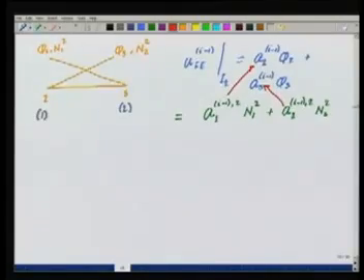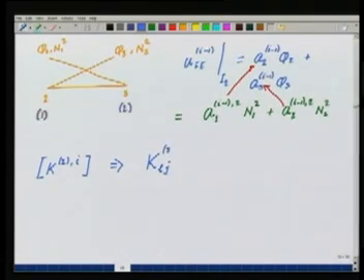Then in the calculation of the element stiffness matrix, by the same token, K for element 2 corresponding to step i will have the components K_lj for element 2 at step i. This will be equal to the integral from x1 of element 2 to x2 of element 2, where x1 is the global x2 and x2 is the global x3, of EA